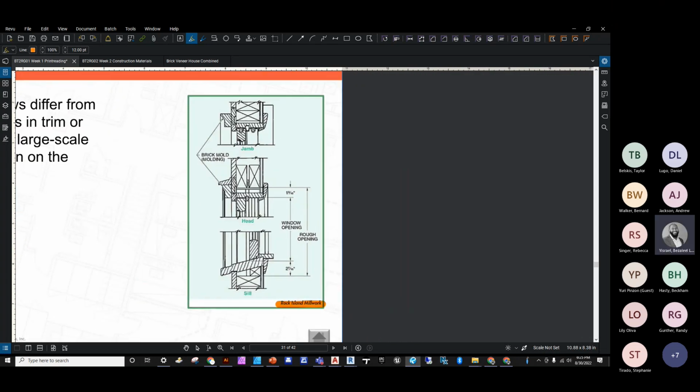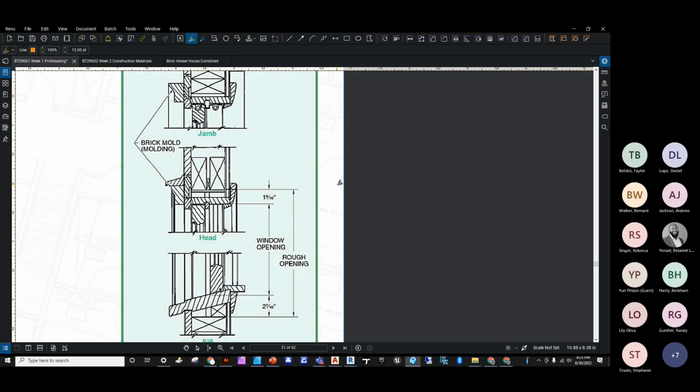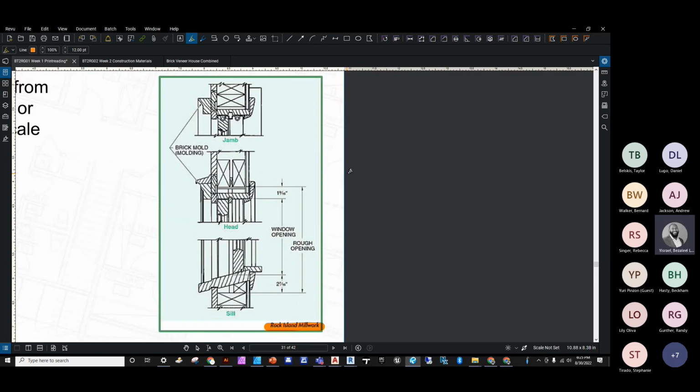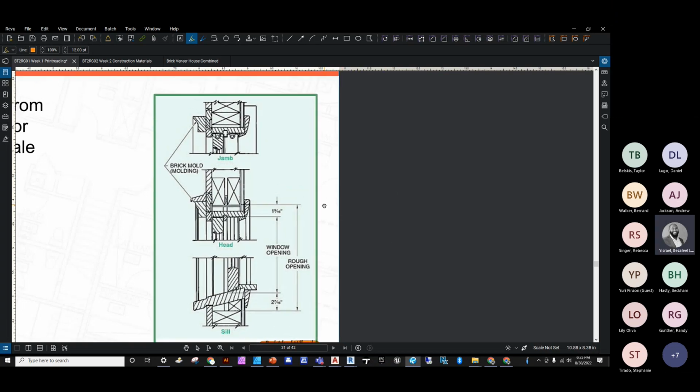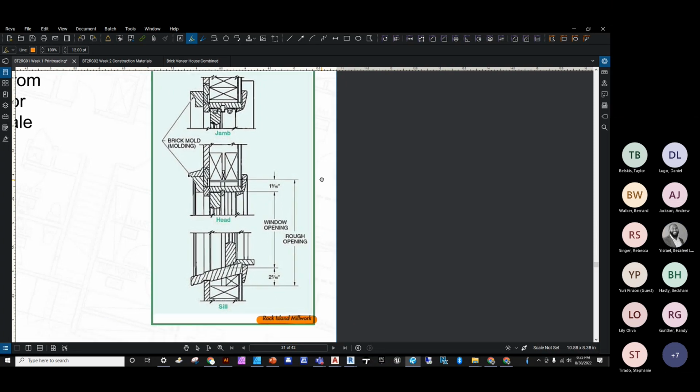Now, the portion of the drawing labeled jamb is basically our section of that window side jamb looking down that has been revolved into one place. Note that the top and the bottom sashes slide vertically in those grooves formed by the window frame members themselves.